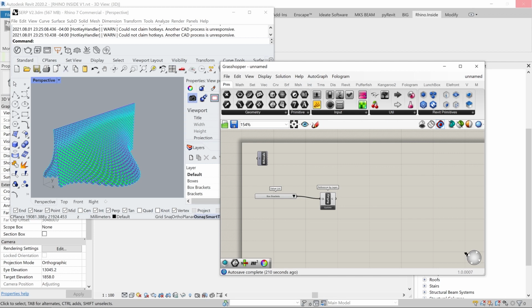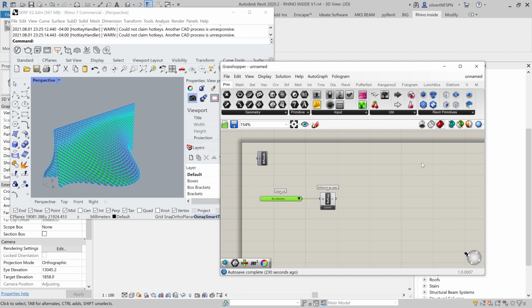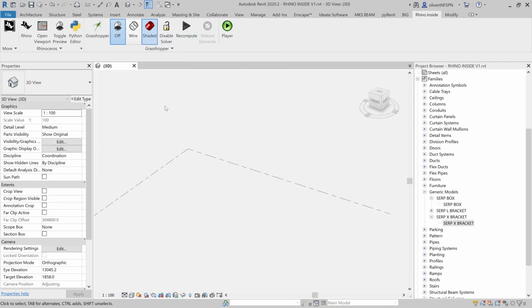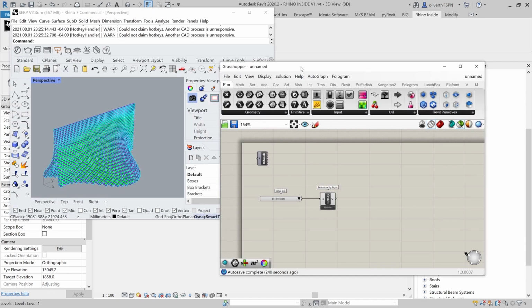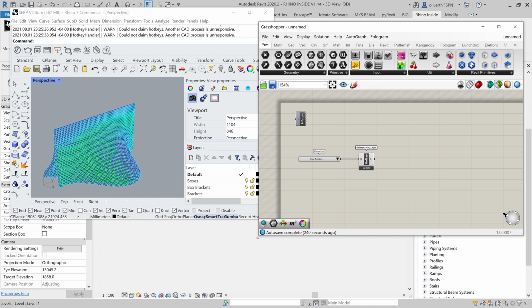In fact, I should have turned off my view properties there because this will burn a little bit of time. I'll fast forward this in the video though. Oh, there we go. But that is a good tip in Grasshopper in general: don't use the solid preview, and also specifically here, I would turn off the preview in your Revit workspace.